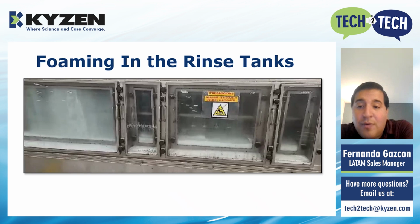Excessive drag out from the wash section into the rinse, or a DI water quality issue. Initially, the drag out of the chemical from the wash into the rinse was addressed by controlling the excessive add-ups of chemical into the process. But also, due to the long design of this equipment, we were able to turn off the last section of the wash to simulate a chemical isolation section, which this old model did not have included.